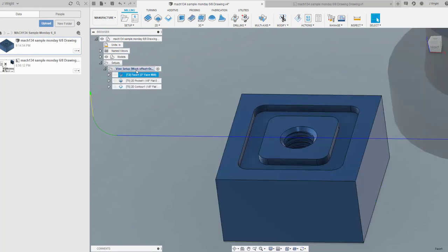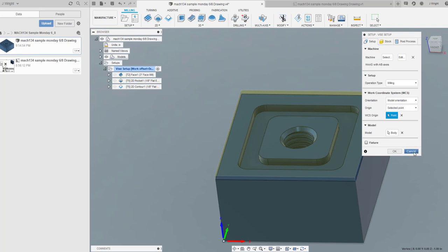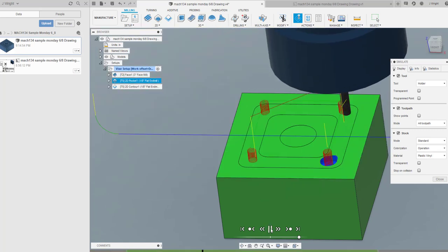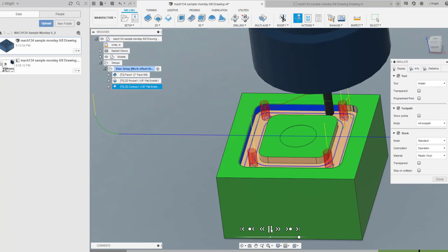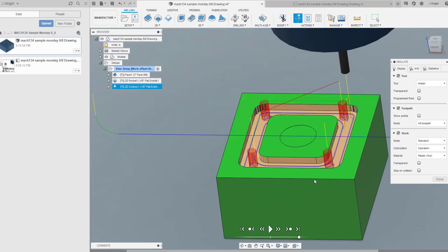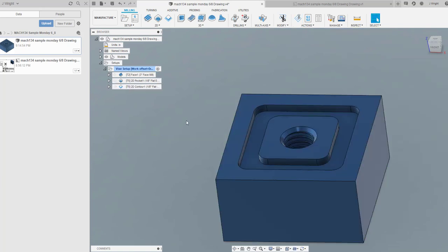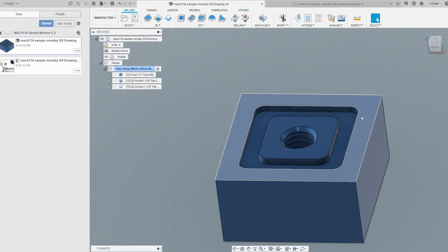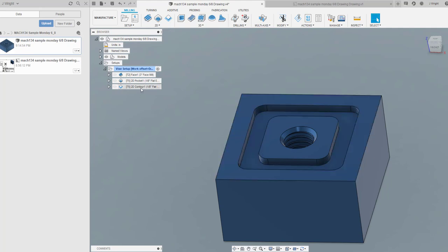Let's go back up to here, and then we'll run it from there. Again, higher speed, just so we can move through it. Face mill, pockets, racetrack, there we go. And so that turns out really, really slick. Now, I talked about and did before, in some small areas you'll have these little bits that didn't get hit by that second end mill. So let's just take a look at what those would look like.